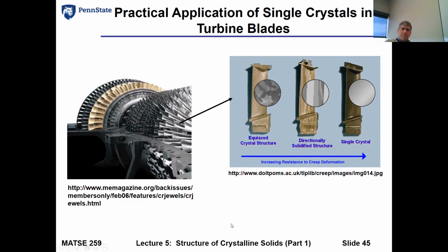But what is the dominant mechanical or fracture-inducing process within these blades is something called creep. For creep, you need high temperature and high stress areas.